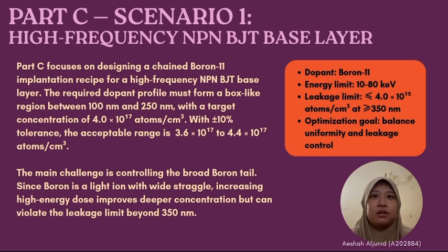Since the tolerance is plus or minus 10%, the accepted concentration range is from 3.6 times 10 to the power of 17 to 4.4 times 10 to the power of 17 atoms per cubic centimeter. The implantation energy must also stay within the hardware limit, which is between 10 and 80 kiloelectronvolts.